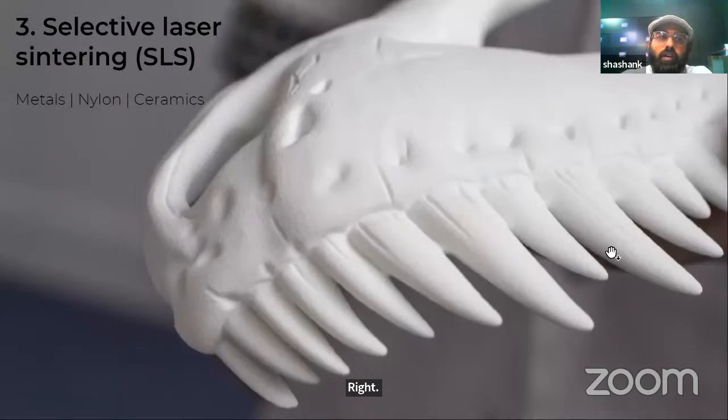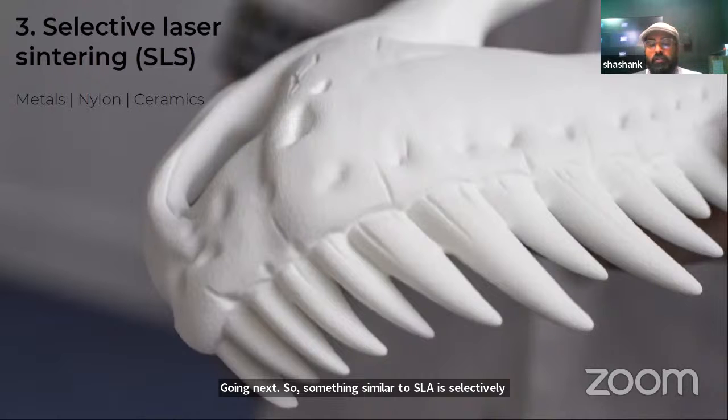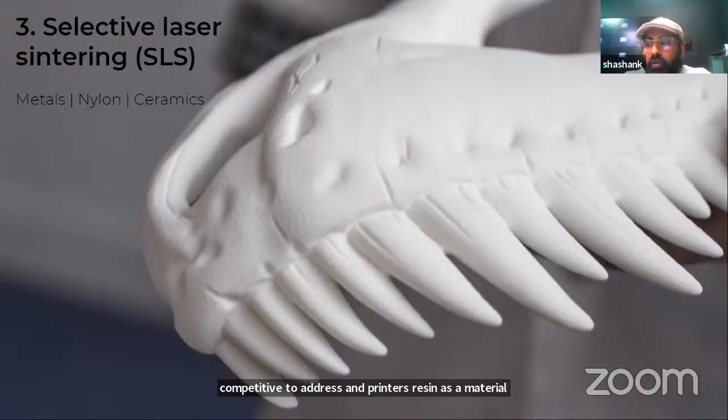Going next. Something similar to SLA is selective laser sintering. It's more or less the same principle, where lasers go on top of the material and solidify that particular area. The difference is that the previous one, SLA, is for resin printers, resin as a material. This one, SLS, is where I can use powders. So what kind of powder? I can use metals, I can use nylon, I can use ceramic powders.